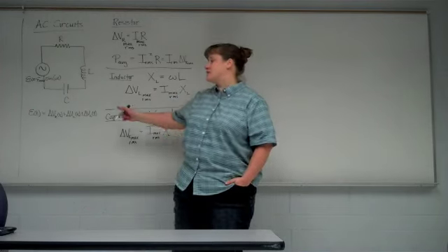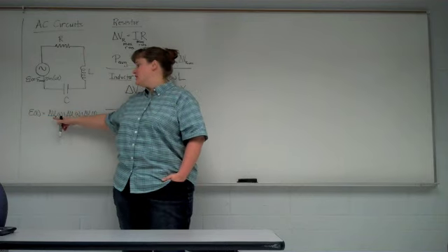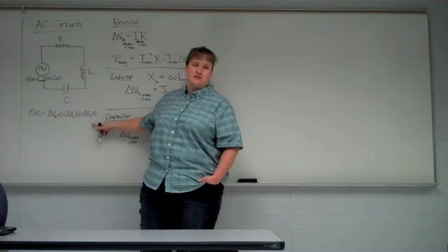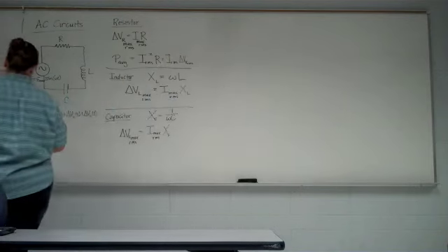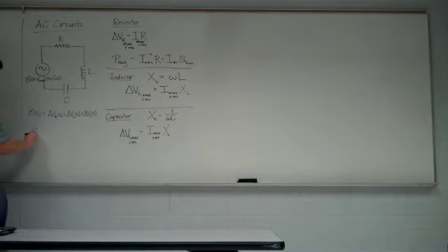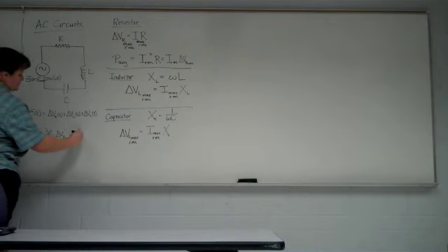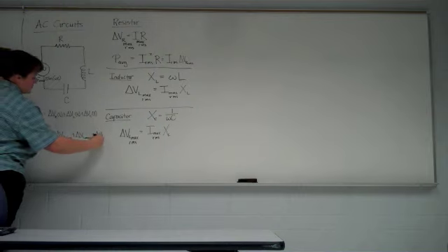But that's not true if you wanted to say the maximum voltage will equal the maximum resistor voltage plus the maximum inductor voltage plus the maximum capacitor voltage. That's not true. So E max does not equal delta V_R max plus delta V_L max plus delta V_C max.